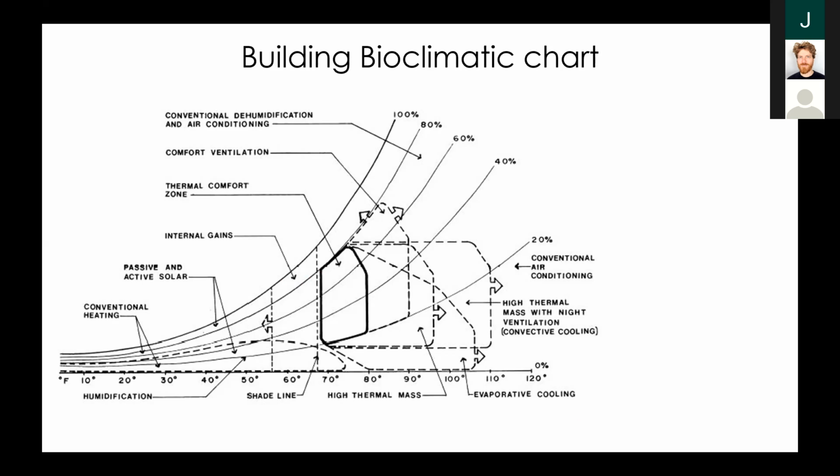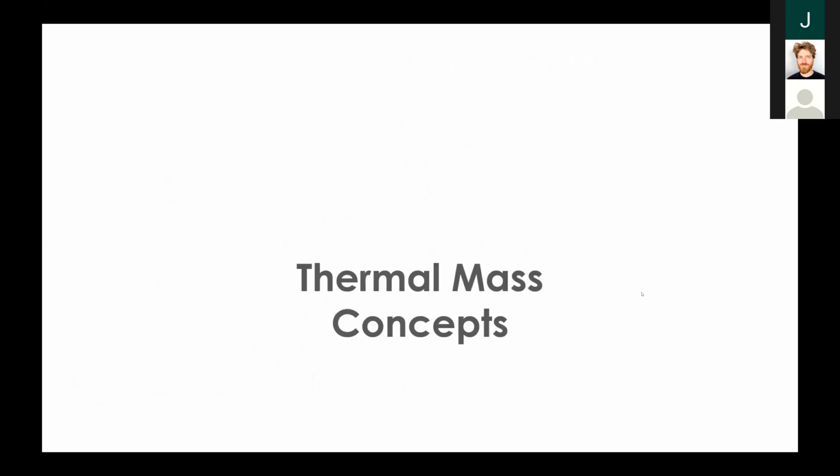The building bioclimatic chart shows propositions for how in a particular climate you can increase that range into other areas by using certain strategies. And you'll notice that a lot of these strategies have similar names to those that you saw in Climate Consultant and worked with for your design project, because it's the same idea that you have in the Climate Consultant chart for passive strategies.